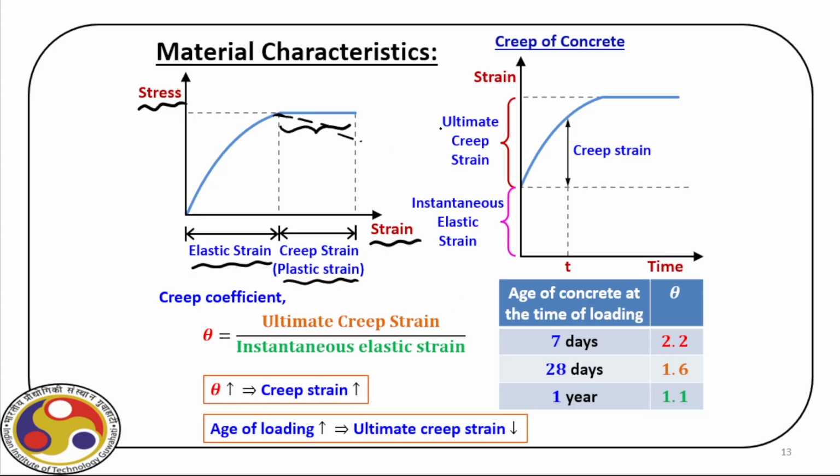So, if we combine these two for this strain, which is actually dependent on time, so instantaneous elastic strain, as you can see here, so we are at, say, time point t here, so we have some instantaneous elastic strain, and beyond that we have the creep strain, and we have this ultimate creep strain which we have to take care of in our design.